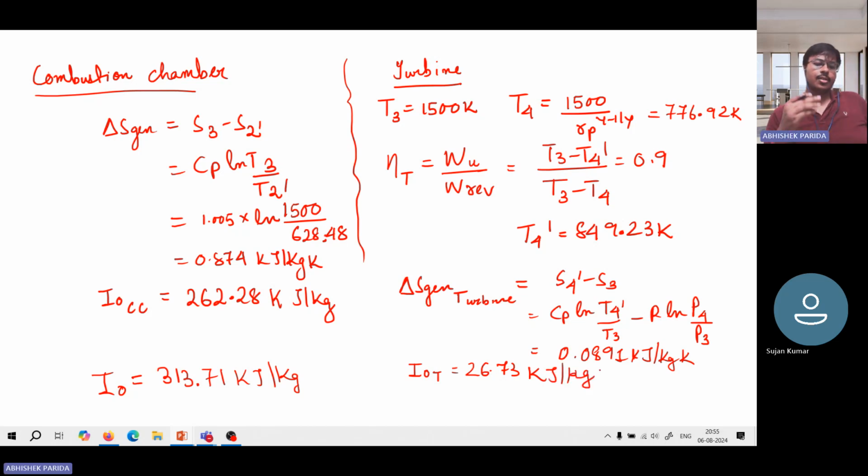Okay, so this much exergy is being destroyed in this power plant. Similarly, you can calculate for any power plant. If you have the data of all the temperatures at exit and all, you can easily calculate. And this is what is done in any industry to know where the loss is in the process. Now you tell me where is the maximum destruction taking place? Simple, it is in the combustion chamber.